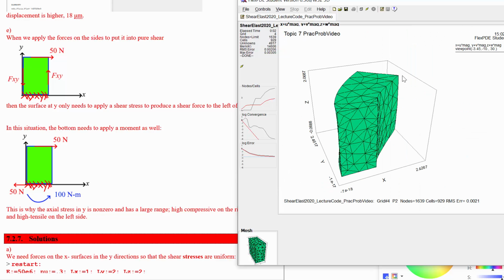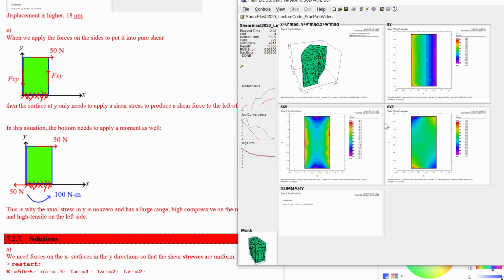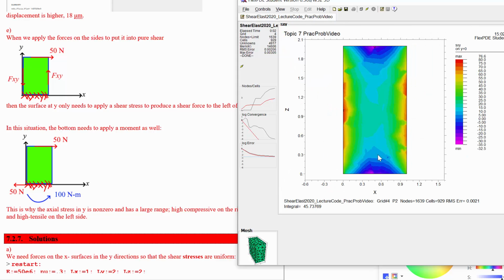The other thing is, because it's rotating, it kind of wants to buckle a little bit, like to bend out in the middle here and pull back in on the tops. And that's kind of what would be modifying the stress in the X direction. So you see this going on here. In the middle, we need to apply more stress. Let's see.